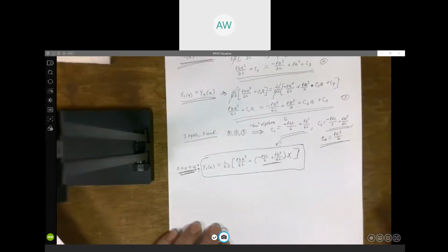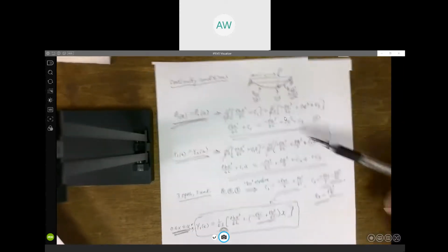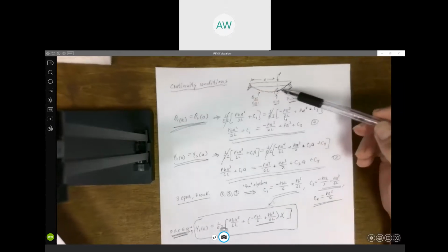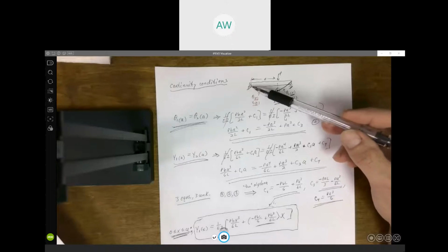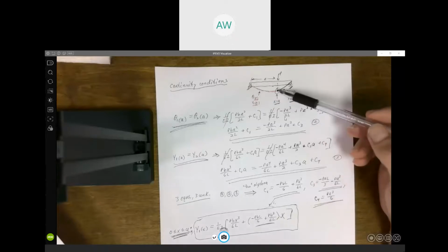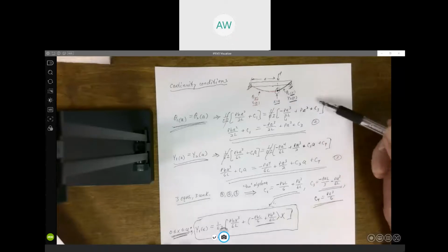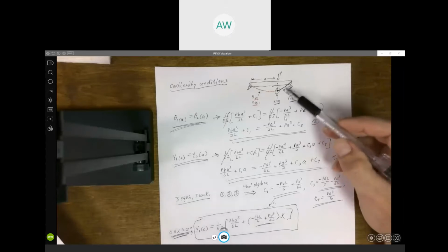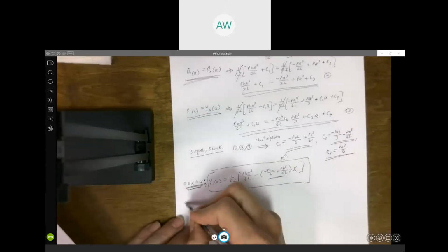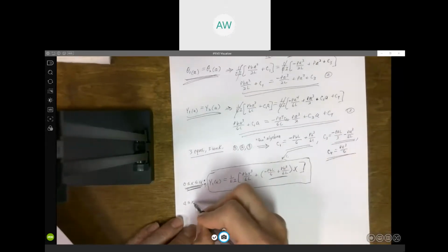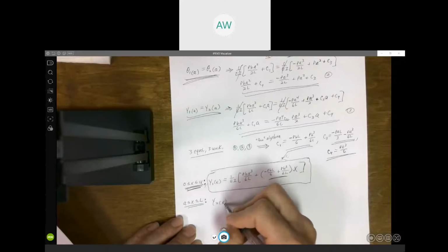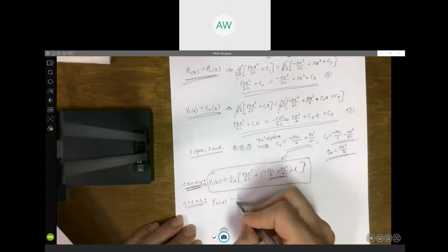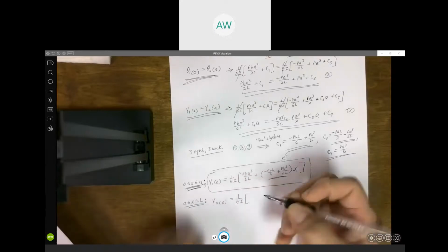If you graph that, what it would give you is this curved line. That's what the beam looks like from x equals 0 to x equals a. Now, we've got a different equation for this section of the beam. So for x values between a and L, that's where we had the second equation. Y2 of x, we call that. 1 over EI.